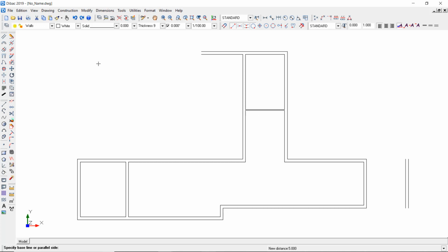I'm going to select the Wall tool again to create a partition wall from this corner to this corner, and then switch back to the Parallel Wall function. Now I type the distance for the wardrobe space and do the 2 clicks. Now I'm going to type a new distance for the hallway width and do the same process.